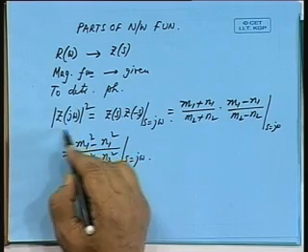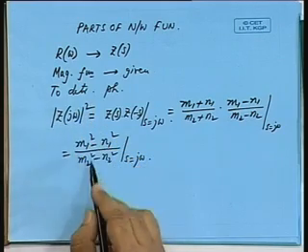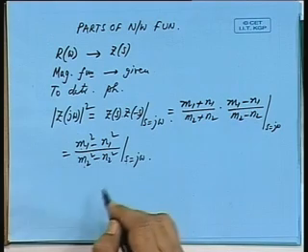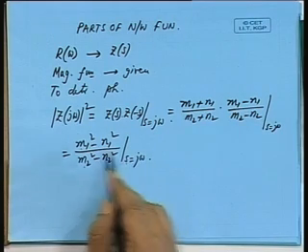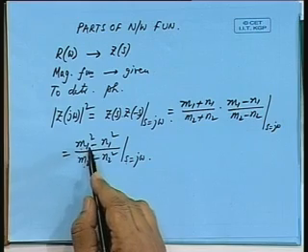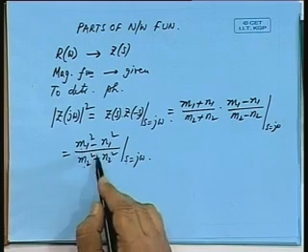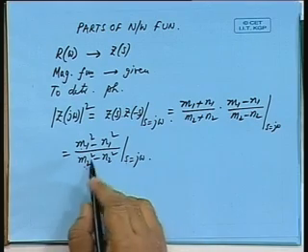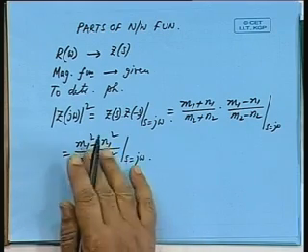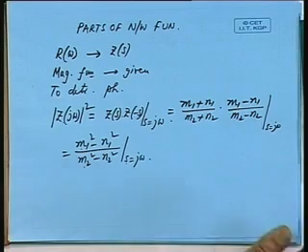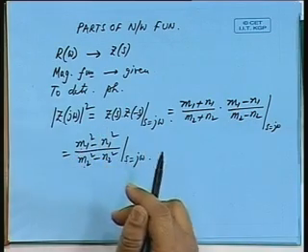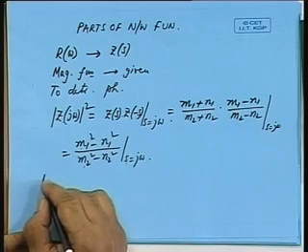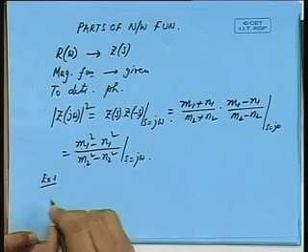So if you are given |Z| squared, it is basically (m1 squared minus n1 squared) by (m2 squared minus n2 squared) at s equal to j omega. If I make a reverse substitution, I will get (m1 squared(s) minus n1 squared(s)) by (m2 squared(s) minus n2 squared(s)). If I factorize and drop out the roots in the right half plane, I will get m1 plus n1 and correspondingly m2 plus n2. It is very simple. So let us take one example.